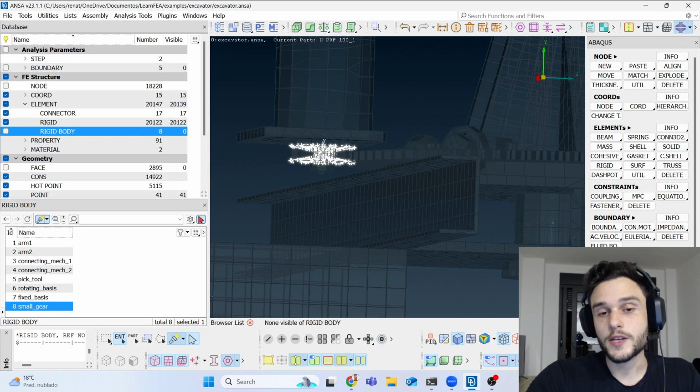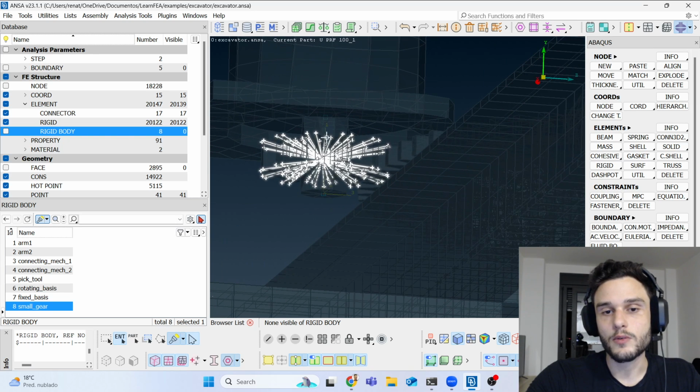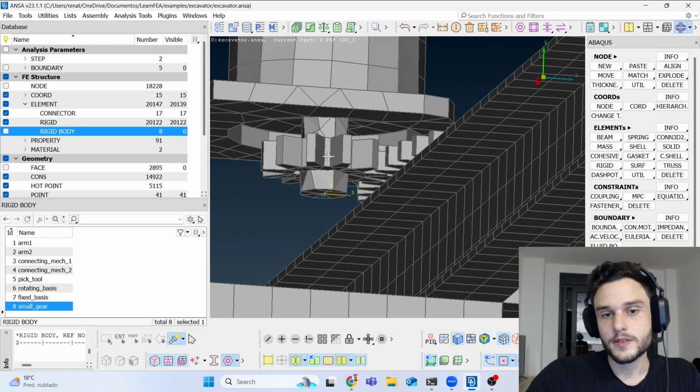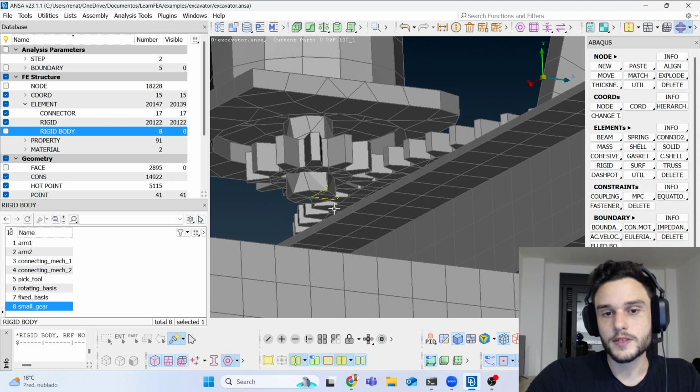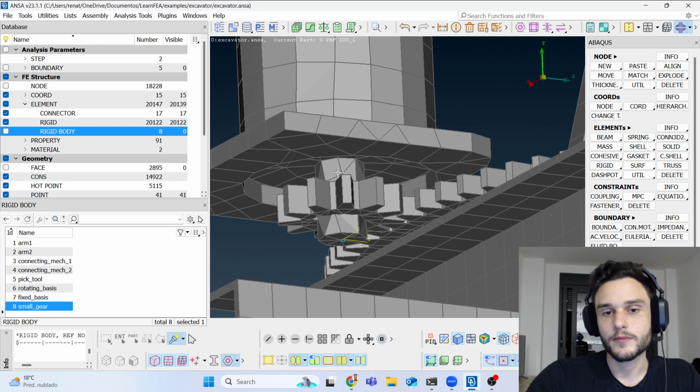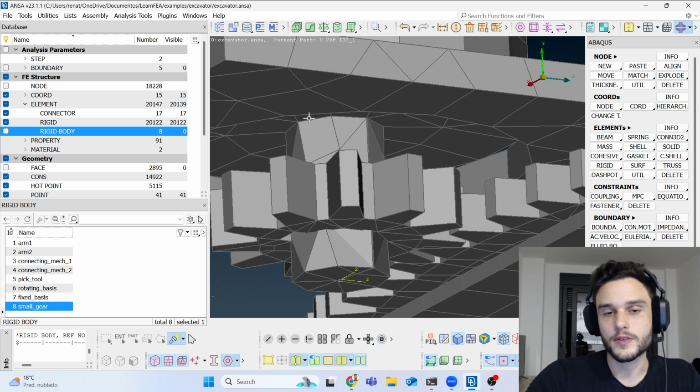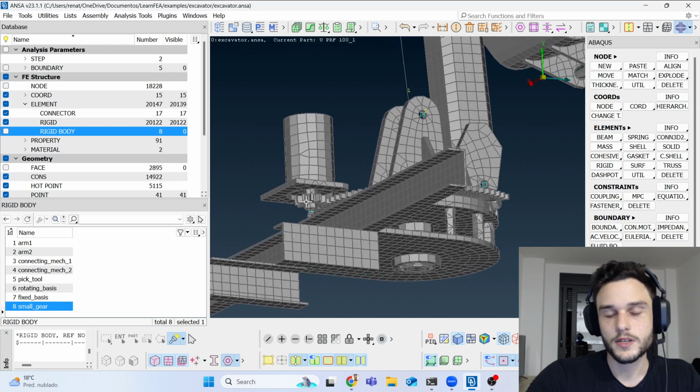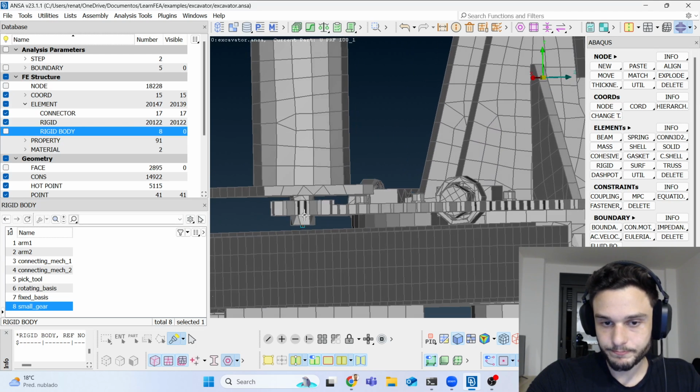And we are using a hinge connector because we want to allow only rotation about this axis here, the x-axis, which is a vertical axis in this case. Because this gear is going to rotate about this shaft that we have here. That's what I wanted to represent.